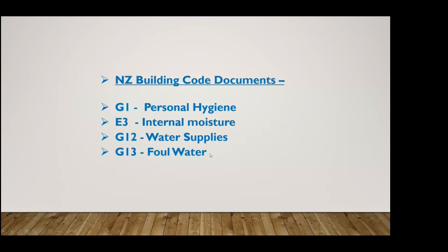But in a lot of more intensive builds, multi-units, certainly any commercial multi-story stuff, it will be designed to AS3500 Part 2, which gives a bit more flexibility in terms of design, allows for floor waste gullies and fixtures discharging within the space. So it's a lot more flexible.